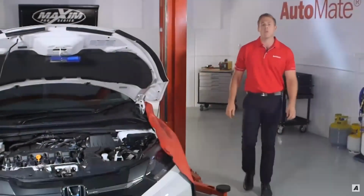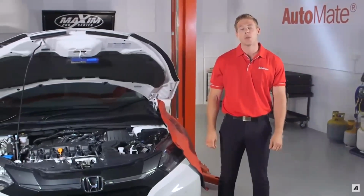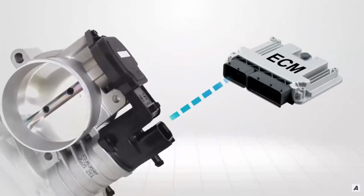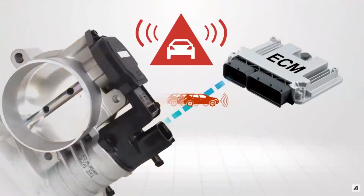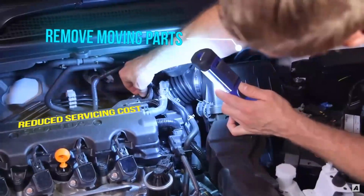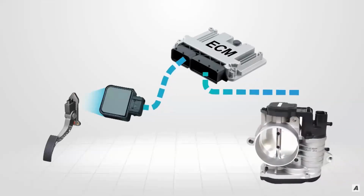The throttle actuator control replaces the need for mechanical linkage between the throttle body and the accelerator pedal. It also replaces the need for an external cruise control module and an idle air control valve. G'day, I'm Zach. Welcome to Automate. TAC systems enable the integration of adaptive cruise control, electronic stability control, traction control, and active braking control with the engine management system. Removing the amount of moving parts also saves money and reduces servicing costs. A TAC system consists of an accelerator pedal, position sensors, an engine control module, and a throttle body assembly.